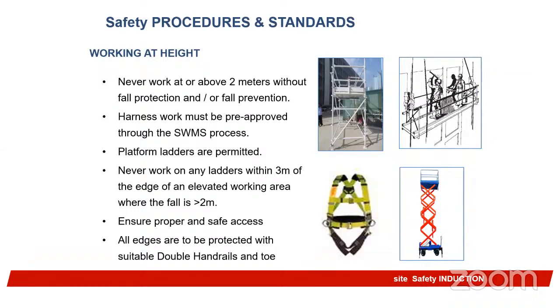But what we're talking about is that you should have safety procedures for work at height communicated during your work at height induction, during your general safety induction. Ensure proper and safe access. All edges are to be protected with suitable double handrails and toe boards. There should be a toe board in case an item wants to fall. The toe board protects them.